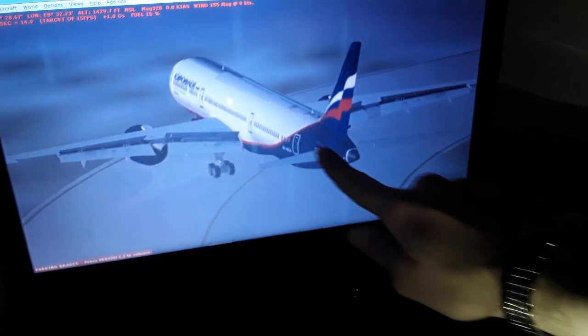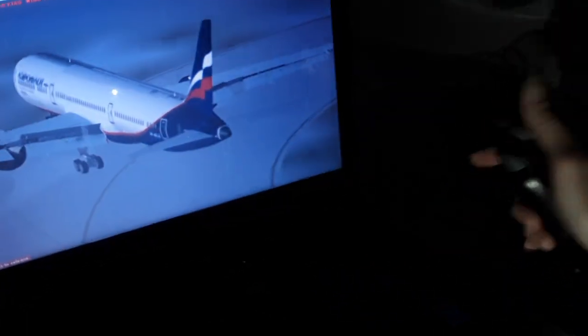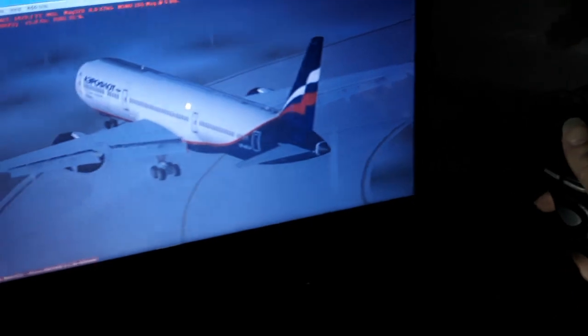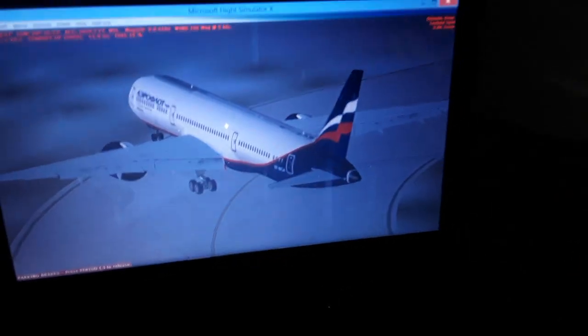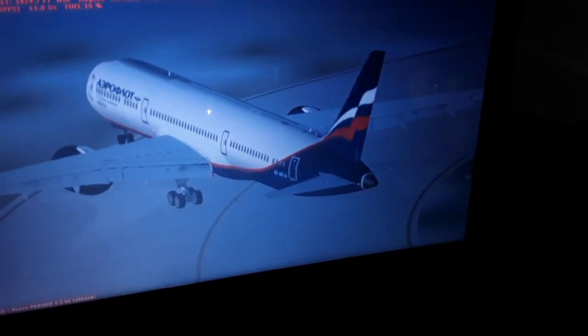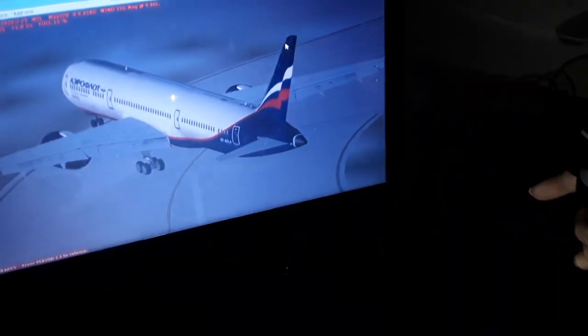So we have one more axis here. It's from nose to tail. It's the longitudinal axis. We make left and right turns like this, ailerons and spoilers. Also you can see aileron, spoilers and flaperons in the Boeing also. One more flight control in the Airbus. So we use aerodynamic lift between the left and right wing by deflecting these flight controls to make left and right turns. So we have all flight controls together, coordinated flight.